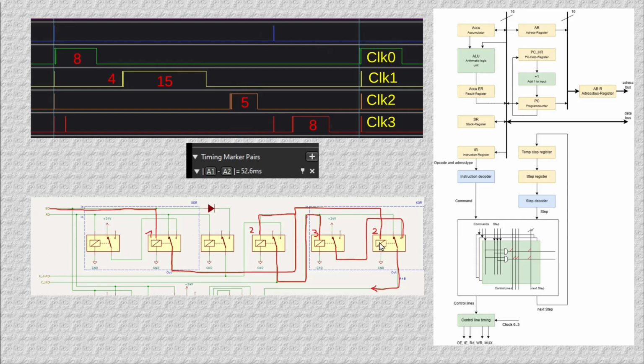If this relay is open, then is closed, then we have the 24 volts to the output. So maybe each relay needs 5 milliseconds. 5 milliseconds after start the first relay, then 5 milliseconds the second relay, and then maybe 5 milliseconds the third relay. And after 50 milliseconds, the 24 volts high are going to low.